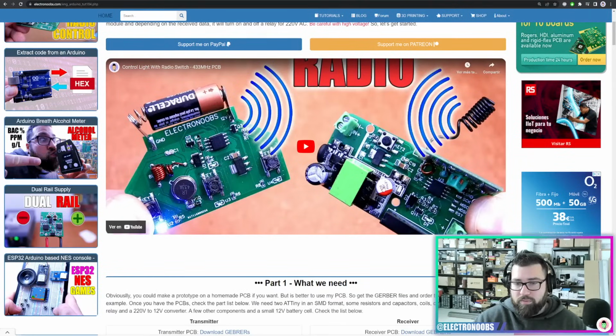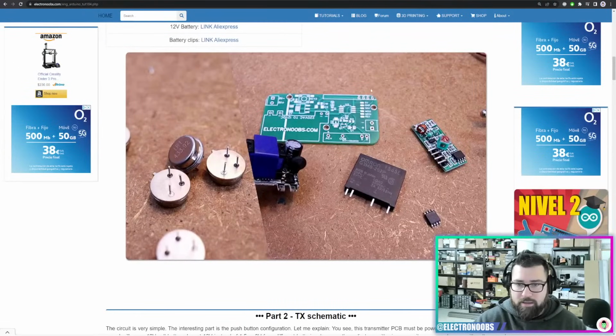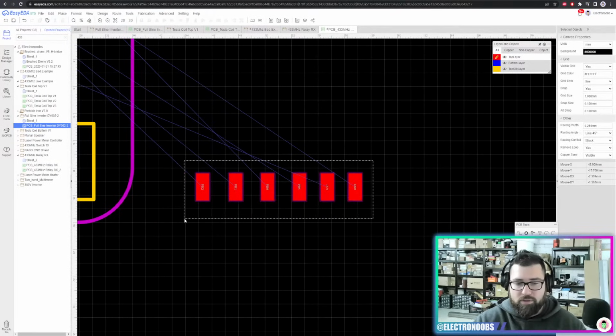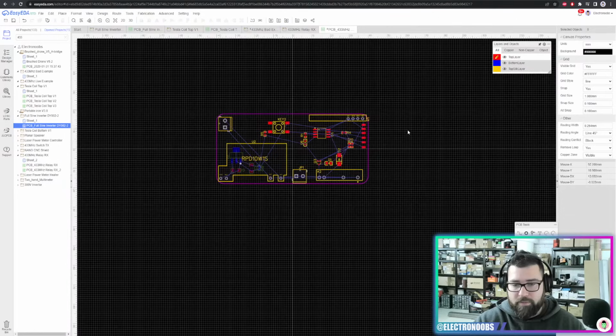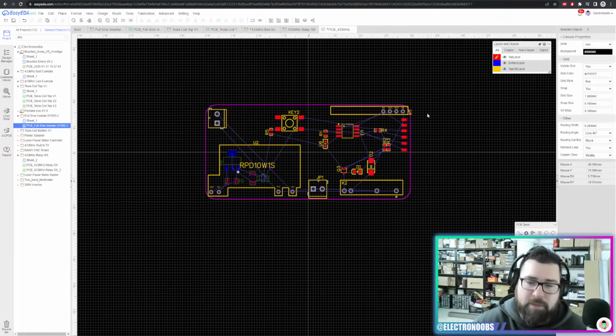The final PCB should be something like this. So I'll place these pads on the bottom side. As you can see, these are the pads for programming. So just take them, rotate them, and place them maybe here. And now we will have our PCB, more or less.